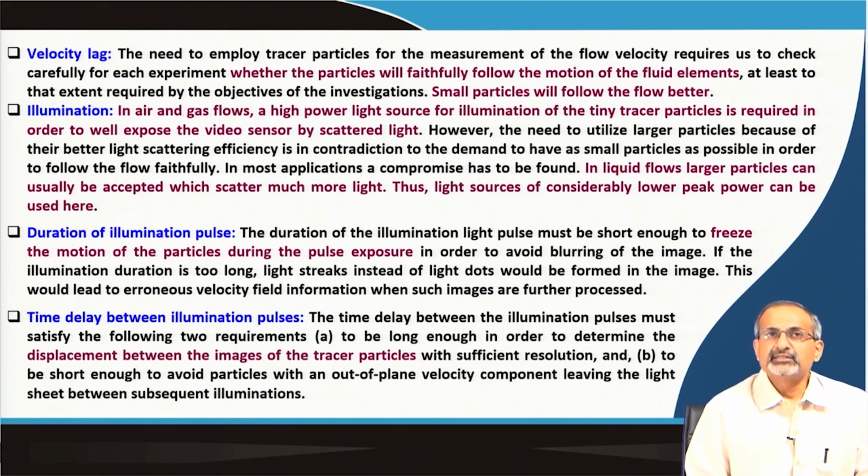This problem is much reduced in liquids because of the buoyancy effects, which are significantly higher there because of the higher density of the liquid. Therefore, larger particles can be comfortably used in liquids, and then much low power light sources may be used for illuminating PIV tracer particles when liquid media are required.